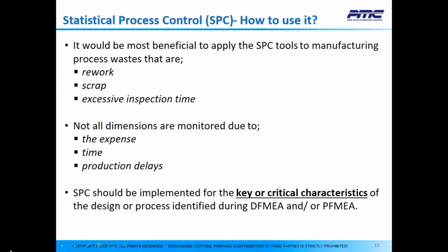So before implementing SPC, the manufacturing process should be evaluated to determine the main areas of waste. It would be most beneficial to apply the SPC tool to manufacturing process waste that are rework, scrap, and excessive inspection time. During SPC, not all dimensions are monitored due to the expense, time, and production delays that would be incurred.